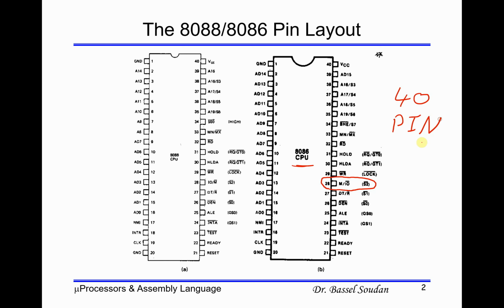We cannot increase the number of pins for the processor, because increasing the number of pins increases the power consumption, increases the spaces or distance between the logics, and has a direct effect on the delay of the chip.